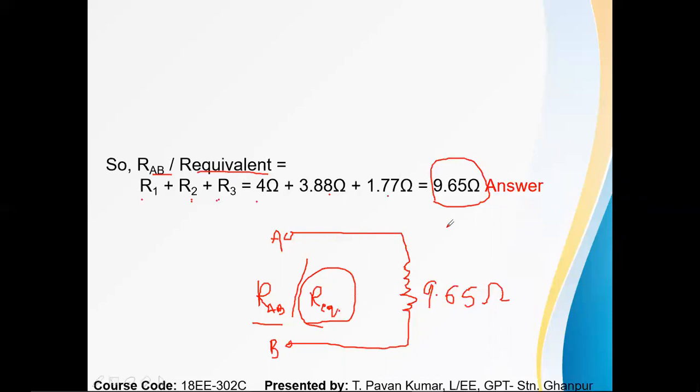So this is the way of solving the reduction of any resistance network, whether it is in delta connection, bridge network, or some other critical network circuit. You can use series, parallel and delta-star. If series-parallel is not possible, you can use delta to star. So the circuit will come under these three categories only: series, parallel, or delta to star, star to delta.